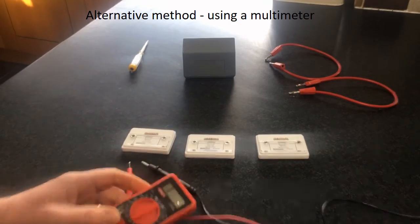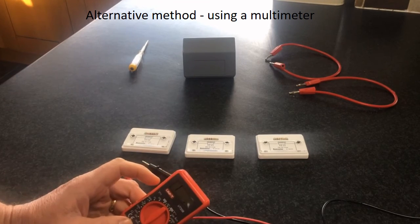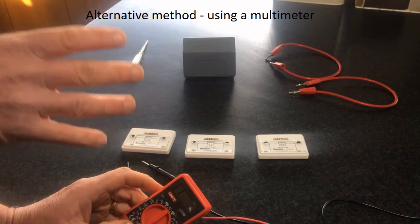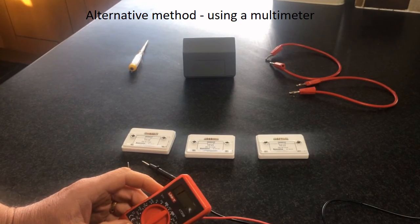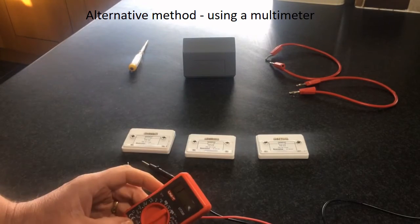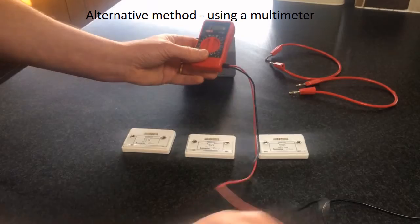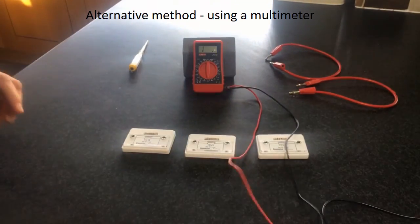By using this, I don't have the problem of overheating by getting too high a current, and also it's a lot quicker and a lot tidier to use. As long as you understand the previous circuit and putting the voltmeter in parallel and the ammeter in series, you could probably get away with explaining this required practical by using a multimeter and measuring them directly. It's a little bit easier to explain. You don't need to record any values. I'll stick all the values on the video afterwards.